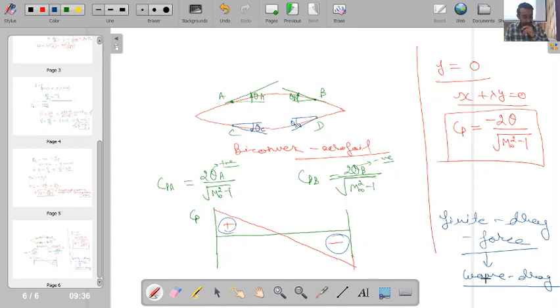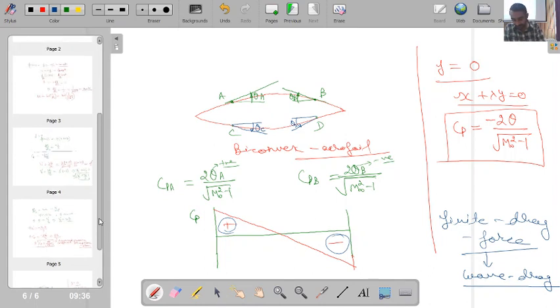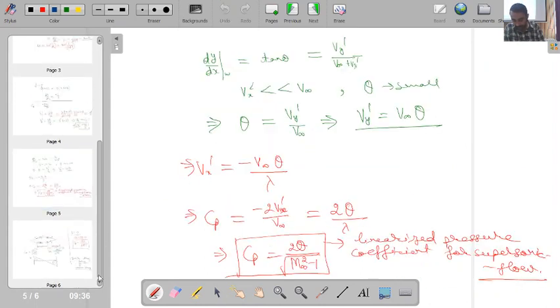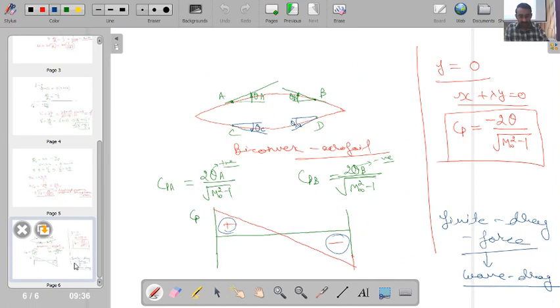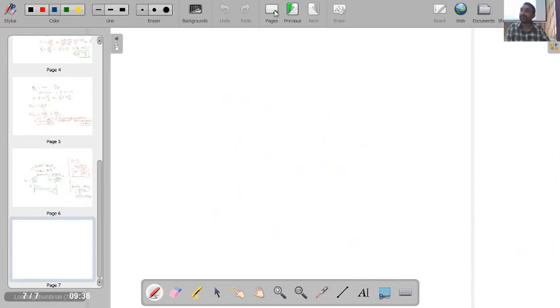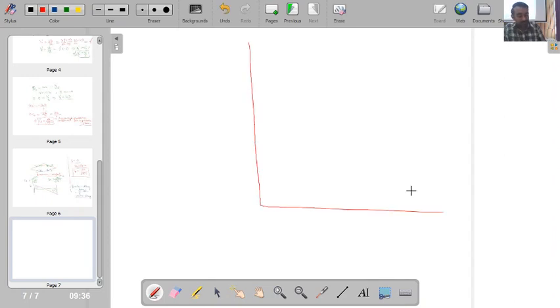Okay, now interestingly, is this point clear? Now if we compare the value of pressure coefficient as a function of Mach number for the subsonic and supersonic regions, what will we get? Say this is my Mach number M infinity equal to 1.